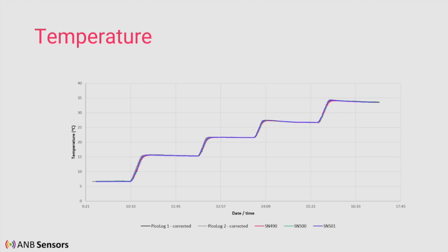We also get asked about our temperature calibrations, the way we temperature calibrate, and each sensor is individually temperature calibrated. We run the sensor across 2 thermocouples. Both of those are calibrated every 6 months. We run those across those standards, and we then put a calibration inside each sensor.